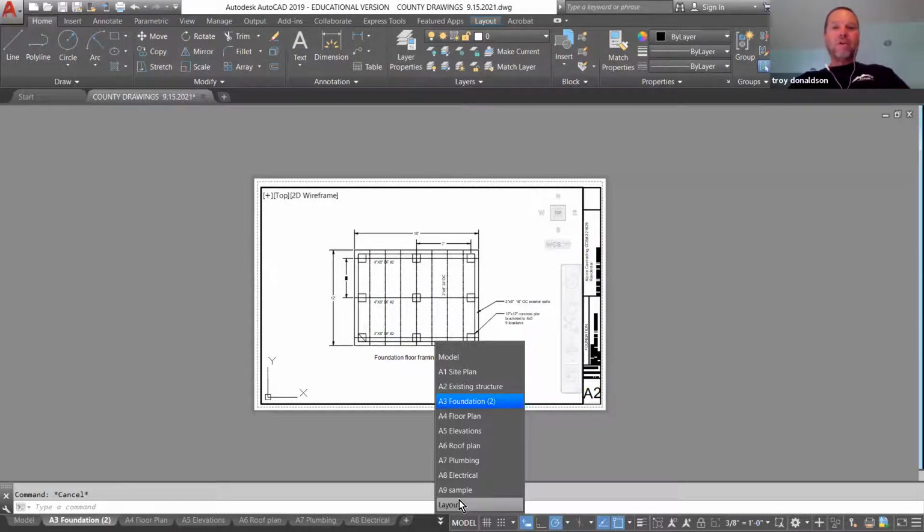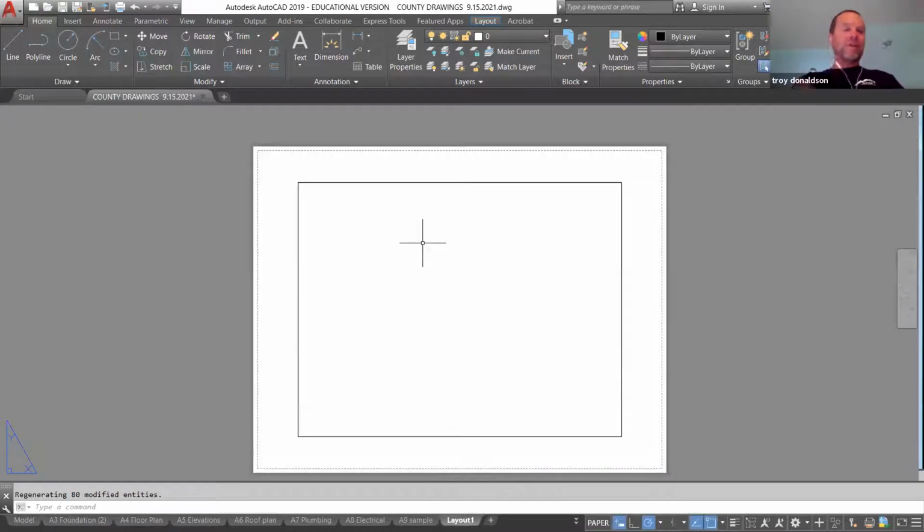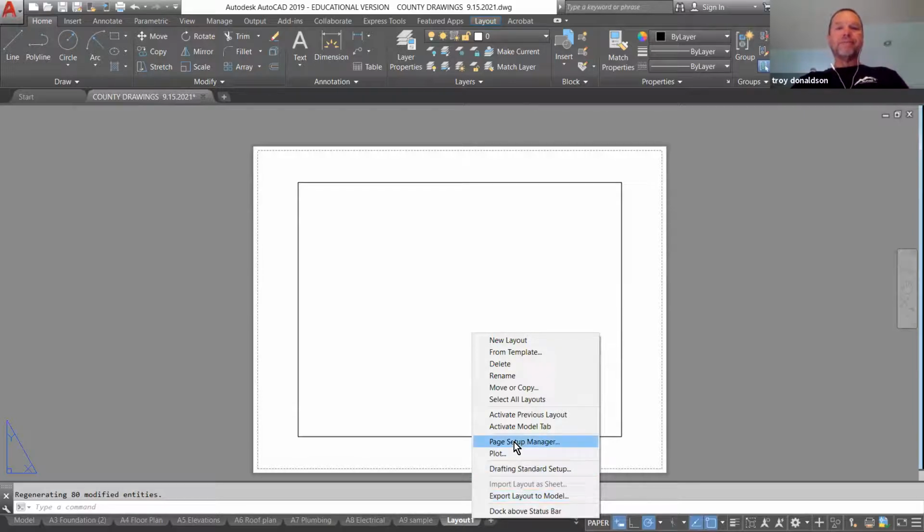All right, so I'm going to go to my new one. This is how often they come to you, and I'm just going to talk about making a title block because that's what your assignment is. So you're going to make a title block, and then you're going to do some drawings, and you're going to have to control text. So let's go through that. When you come into a layout, you can see that this is a small piece of paper, 8.5 by 11, and I can tell that just by proportions. If I want to change that, I just right-click and go into Page Setup.